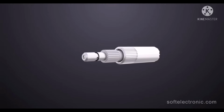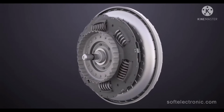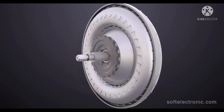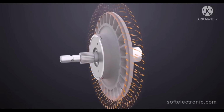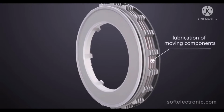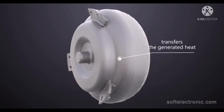The transmission oil enters the torque converter through openings at certain points on the different shafts of the gearbox. It has three main functions. It participates in the hydraulic control of the torque converter by pressure regulated from the mechatronic. It provides the necessary lubrication of moving components. It transfers the generated heat from the torque converter to the cooling system.